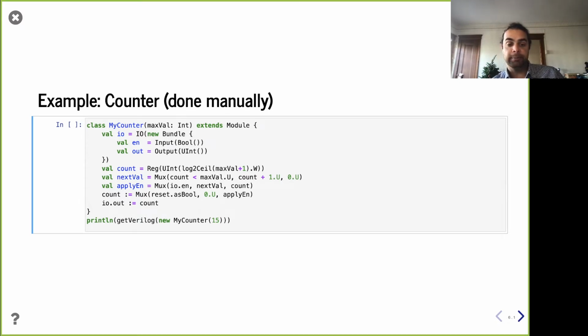So in our case, we're making a simple wrapping counter where it's going to count up to the value we give it. In this case, we're saying, hey, max val. And then it's going to handle all that, right? So let's talk our way through this code. What would be inside of a counter? Well, it's going to be a register to hold that count, and it's going to need an adder to add on the value, right? So if we have count, I want count plus 1. We'll do that. Count plus 1 is going to be an adder.